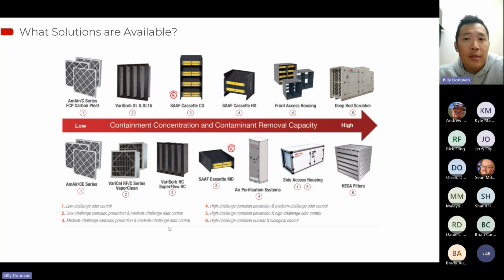For those odorous applications, AAF makes an ashtray style filter. So you still get those MERV 8, MERV 13, MERV 15, whatever efficiencies, but you can combine that with a carbon media. Nice about this is, when wildfire season gets started, an owner can simply go up to their equipment and replace their regular filters with some of these carbon filters or a carbon final, and everybody's happy.